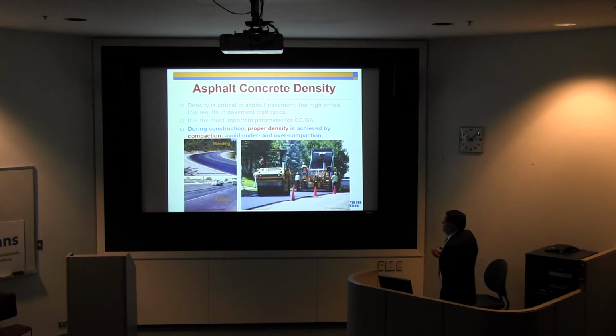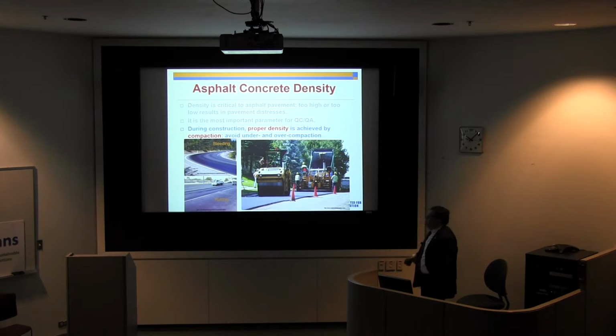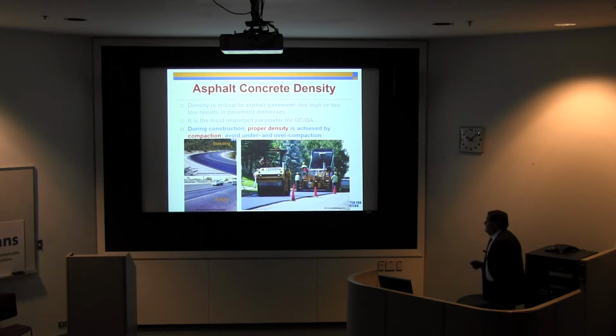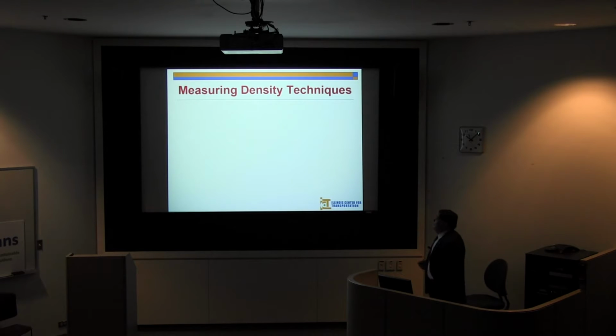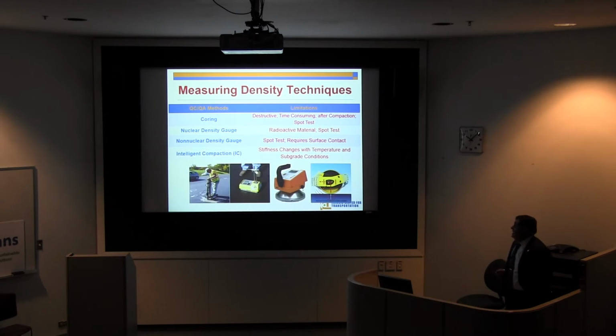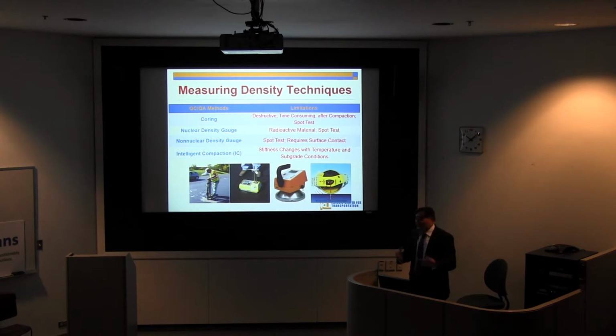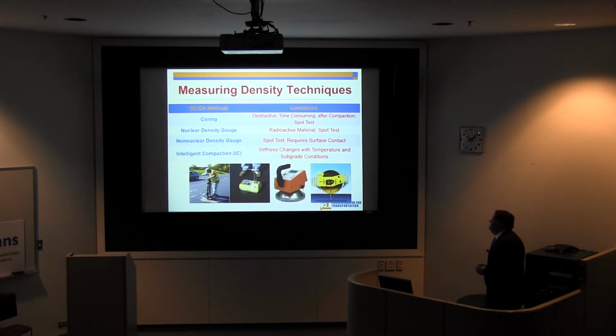So during the construction, it is important to get the proper density. And we're trying to avoid under or over compactions. And that's not an easy job for people who work in the field. It really requires some good experience. So measuring density techniques, currently we have cores that you go to the field, take cores, but how many cores are you going to take? I mean, you're going to change it to a Swiss cheese if you're going to take many cores. So we need to be, I guess, reasonable about this.